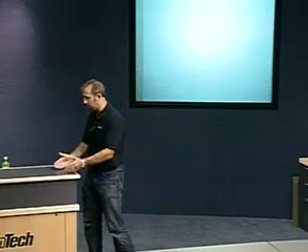the right numbers. The final thing was to make sure that you keep your real and your reactive impedances separate. You can't just say, well, I got this magnitude of 754 on the inductor and combine it with the value on the capacitor, or just combine it with a resistor and bring it down to a wholly real impedance. That's not going to happen.